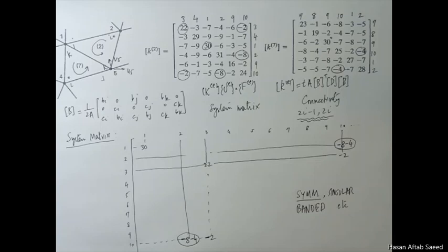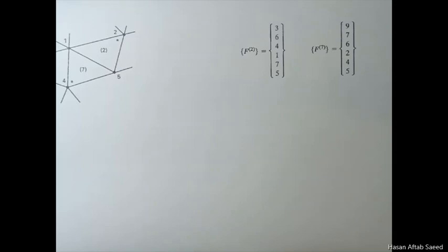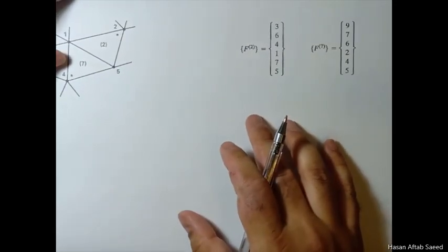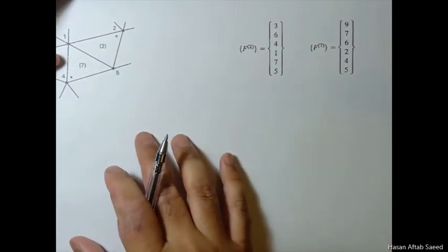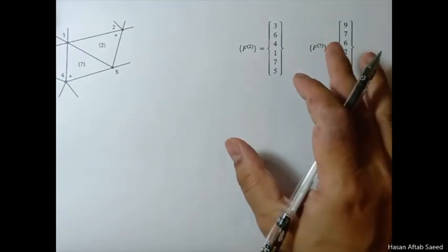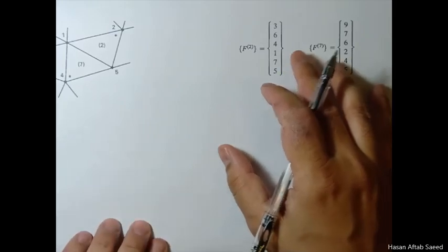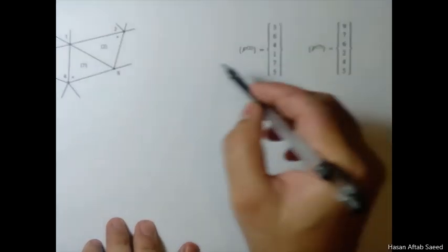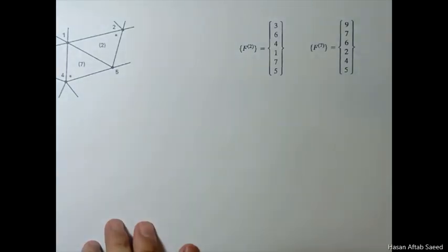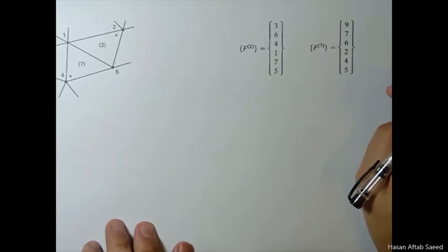And that is the assembly of forces. You not only assemble K matrices, but you also assemble force vectors, and that is also a similar process. Let's say we have these force vectors for the second element and the seventh element. Now these force vectors are a result of body forces, pressure forces and thermal forces.